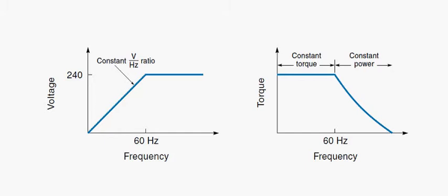So in front of you have two graphs. There's two regions of operation here: constant torque, constant power. In the constant torque region, we have a volts to frequency ratio that is kept constant throughout its normal operating range. Okay, the volts and hertz can be gleaned off the motor nameplate. So here we say it's 240, and here the base frequency is 60. This is obviously 240 to neutral as opposed to phase.